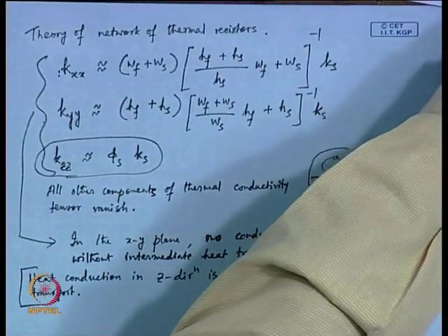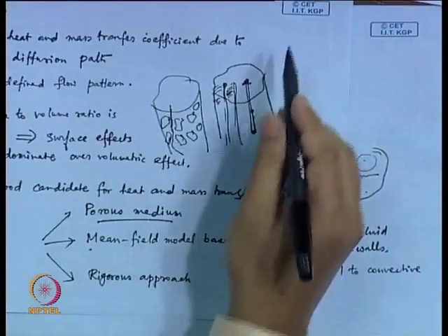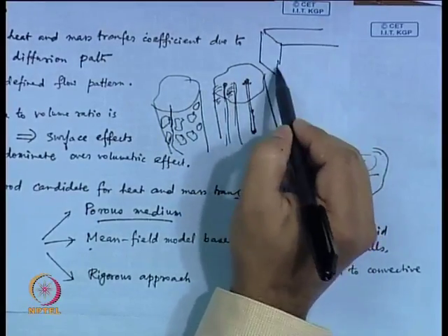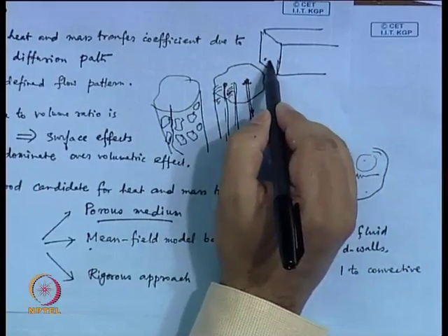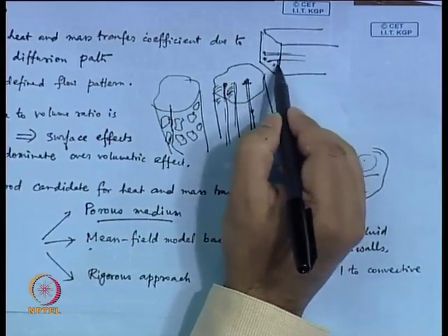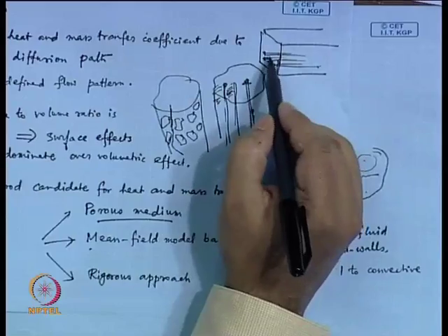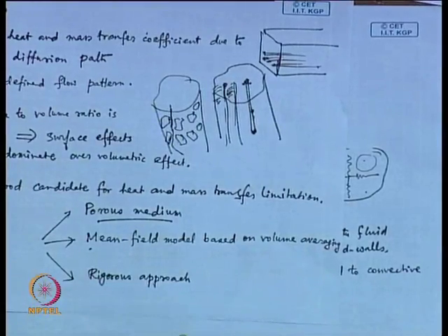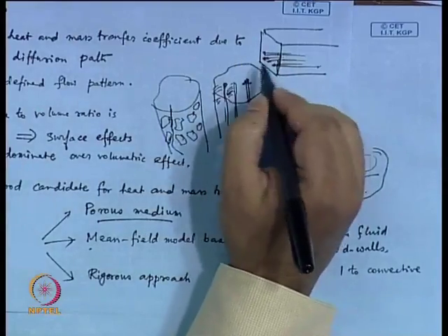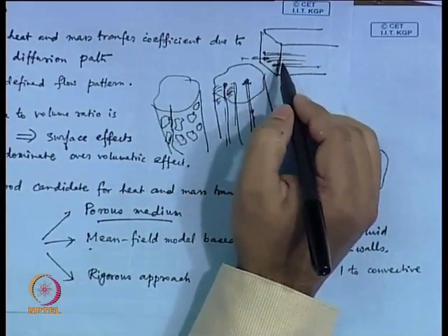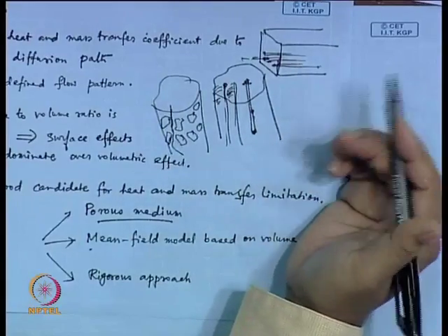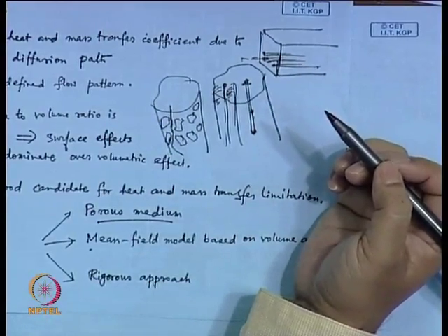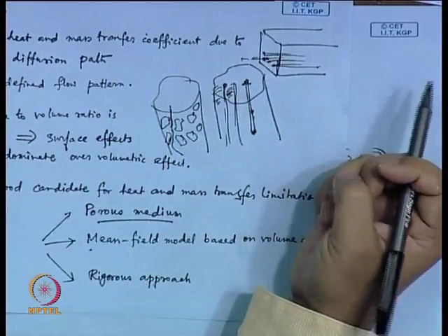If you look at this honeycomb, the way these honeycomb reactors operate is that suppose you have a block of this structure and you have several such channels running parallelly, very well defined channels, you know exactly the dimensions, and the inner wall of these channels is coated with catalyst material. You have dipped this whole structure into the catalyst material and you have a coating of that catalyst, and that is acting as a catalyst when the flow is taking place through these channels. Now, there will be a heat of reaction, maybe exothermic or endothermic. So either heat would be generated or heat would be taken by the reactants. So either you have to take out the heat, unless the heat of reaction is small, or you have to give the heat.